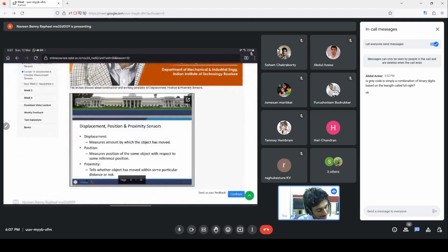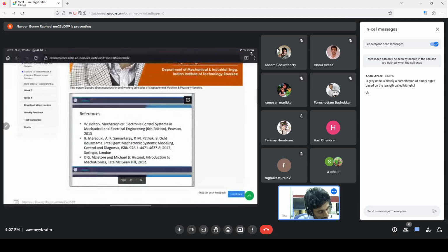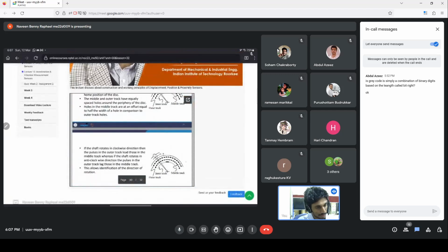That is, we had to identify the position from this setup. So in the end, I guess it depends on the manufacturer. As in, we had 3 outputs from the encoder, and we had to put them in a microcontroller and program it in such a way that we know what position it is.